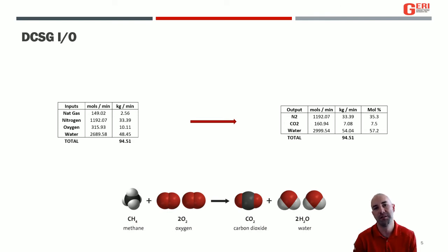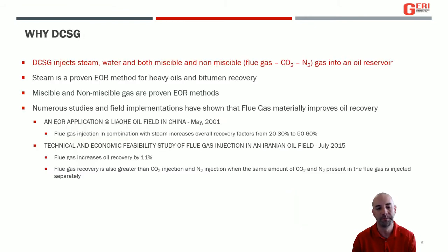We've done 4 pilot tests to date, roughly 20 days of steaming for each pilot. We haven't noticed a significant degradation in our piping from the CO2. In fact, we've found that when you have excess oxygen in the system, that seems to have a much more negative impact. So if at all possible, you try and feed the direct contact steam generator with a little bit higher natural gas than what you're going to pump in from the air side. So you want to have on the output side a little bit of natural gas just to keep your oxygen in check. That's the biggest takeaway from that.